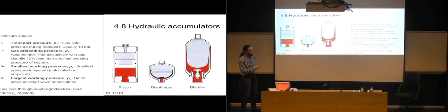But it is important that you have regular servicing intervals where the pressure of the gas inside the accumulator is checked, just to see that it is within the operating range.